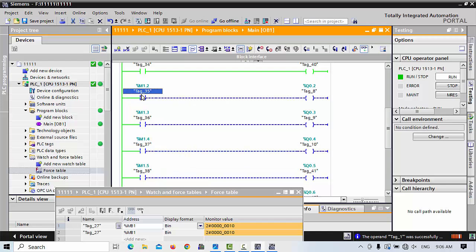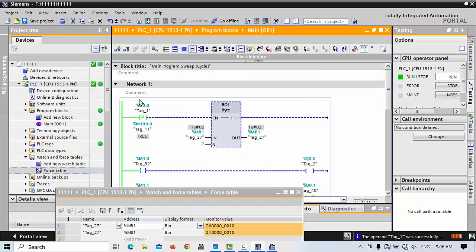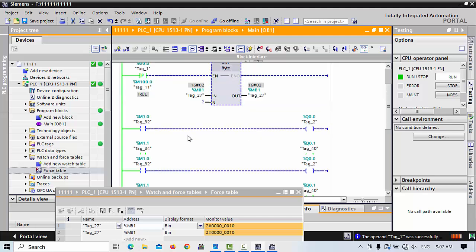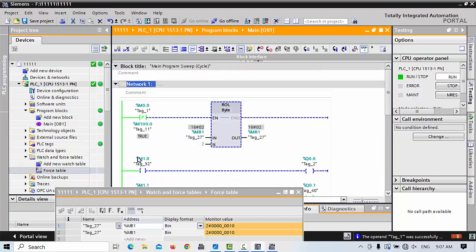Also you can give tag names, saying which number is the signal and which one is the signal for using these relays forward. Also you can make notes here in the network, saying which name this network is running, easy to understand. To make it small, this is network 1, network 2, and when you like, you can hide them, and many more things.